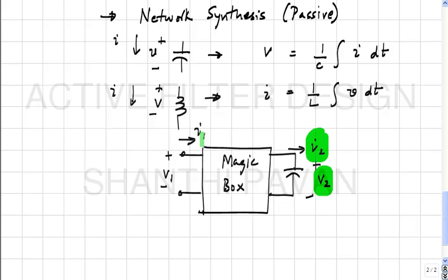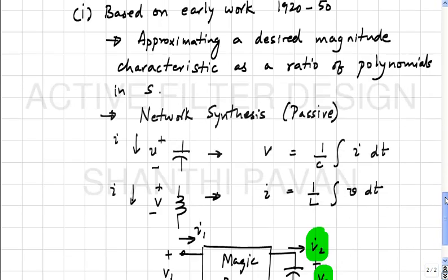You understand? So this therefore means that even though you don't know it as yet, it must be possible to use transistors, bipolar, MOS, JFET, whatever, right, to realize an incremental box which will interchange the roles of voltage and current, and therefore get rid of this problem of inductors. Okay, and now once you know this trick, it's just a matter of synthesizing all the filters that you want. Okay, so this is one approach to doing active filters, and one of the first approaches to do this, right? And so this whole active filter design in the beginning was motivated by trying to reduce the size of the inductors.